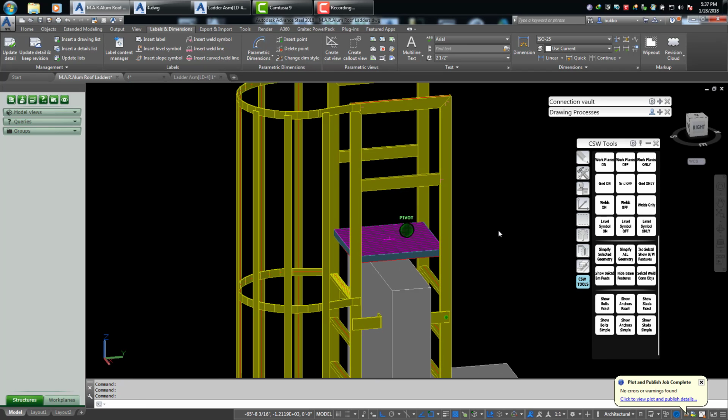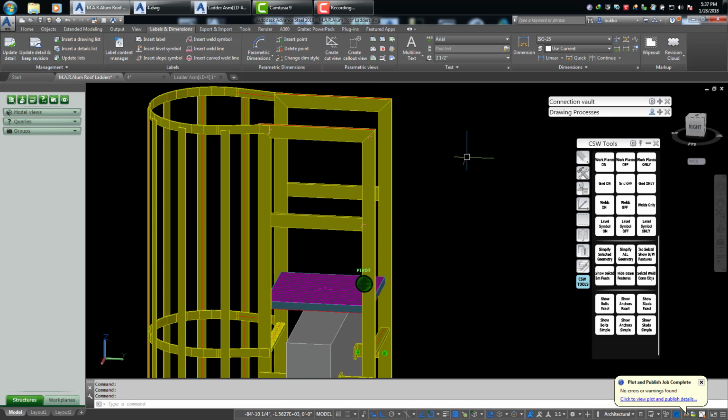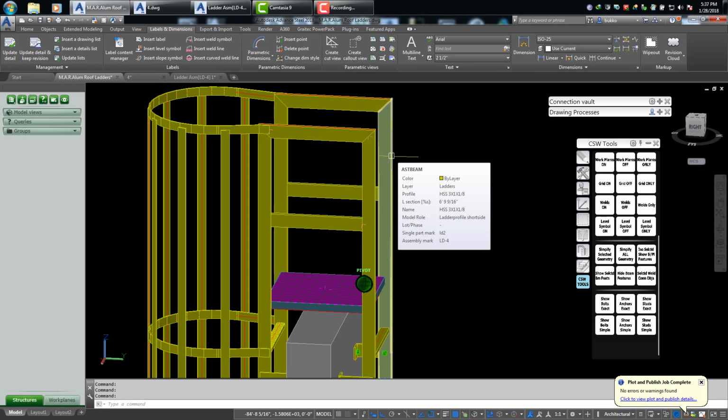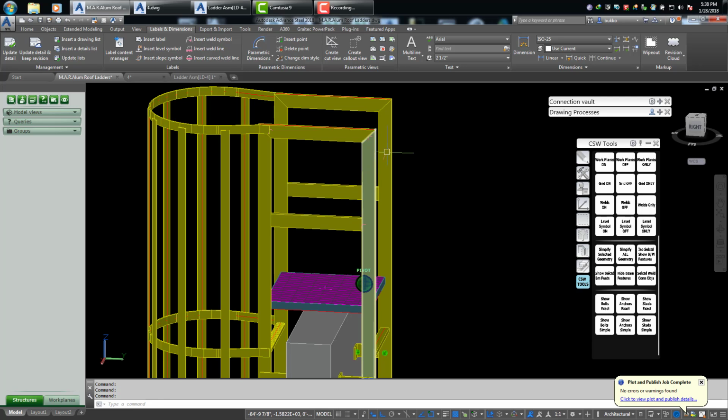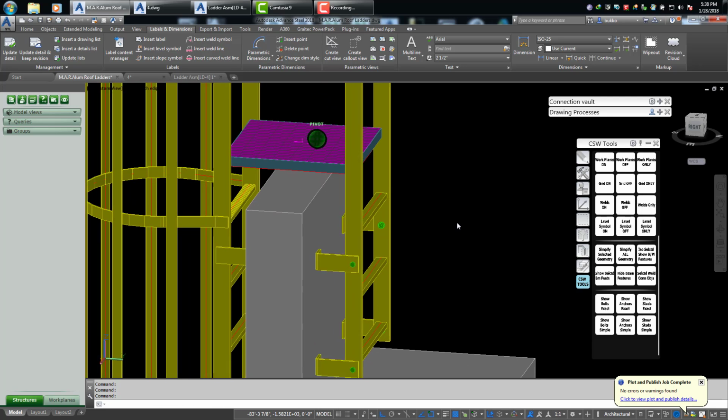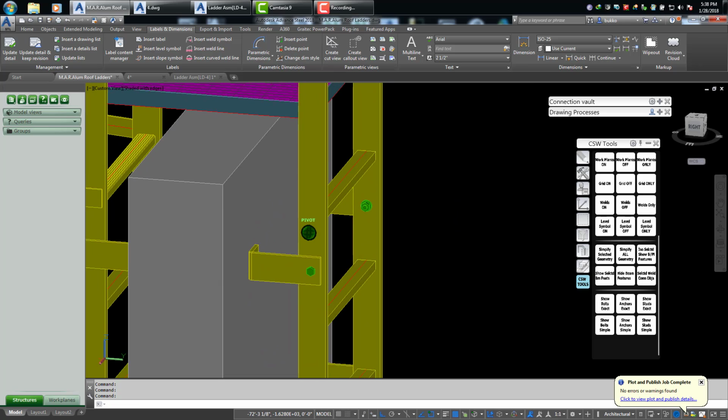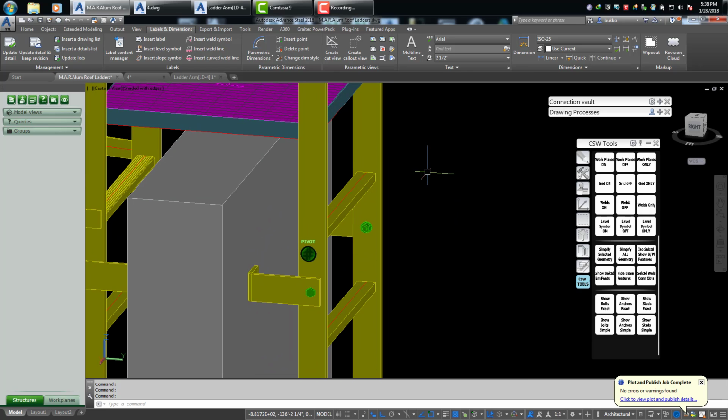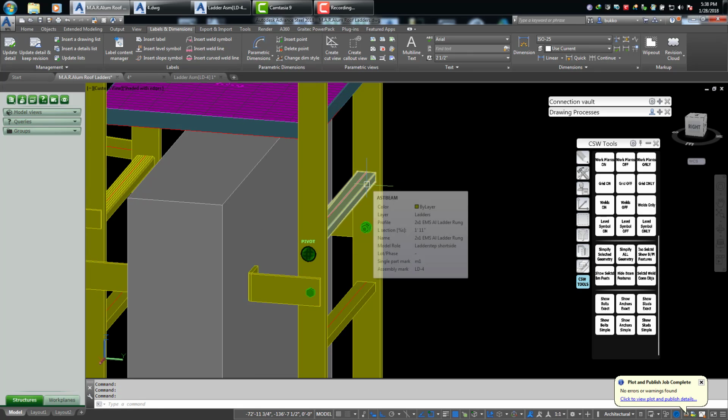Now, to isolate the ladder profiles to make dimensioning more accurate, especially with your dimensioning requests, I've created the back side of these ladder profiles. It's called ladder profile short side, and both of these are that. And as far as the rungs go, to get independent running dimensions on the rungs, I've created the ladder step short side.